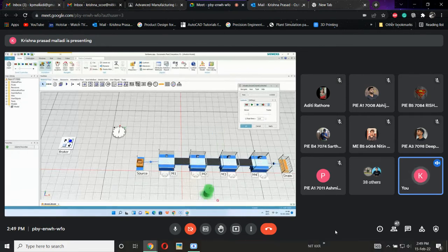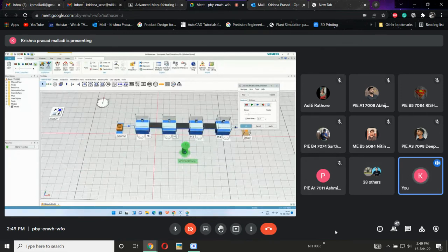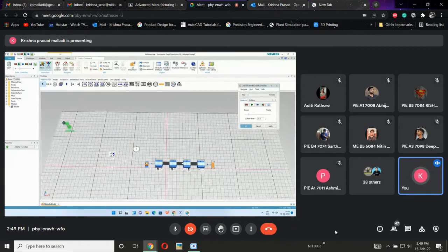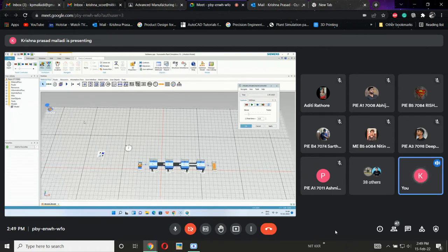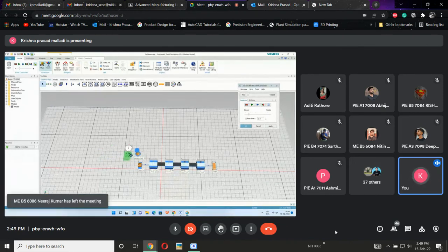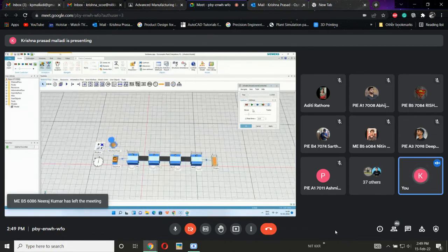Based upon this workflow location, they will decide the free movement area. Now I place it here, so the workers will directly enter here. If I place them at this position, he will come like this. If I place this guy at this corner, this is what is going to happen. Now, if this work pool is at this location, what will happen because of this? This material handling will have a blockage. Now I want to reduce it. That is why I am placing this work pool location somewhat near to my model. So this is easier for me. Now I run the model.